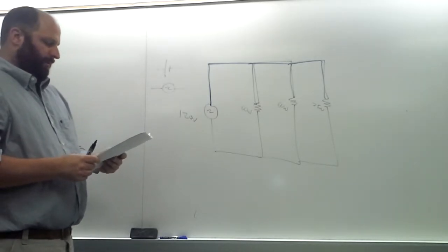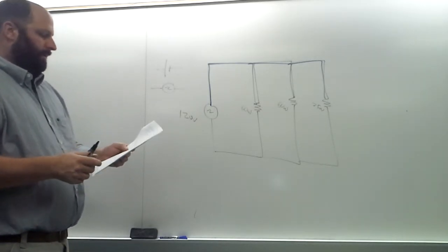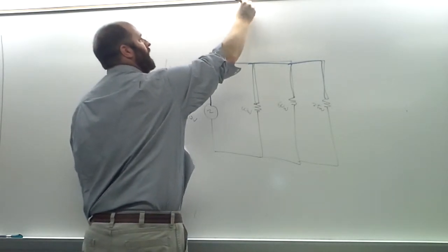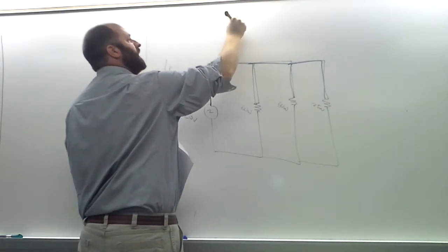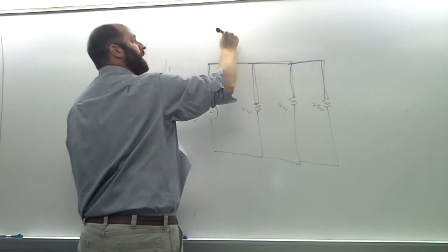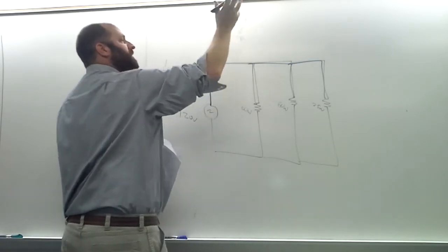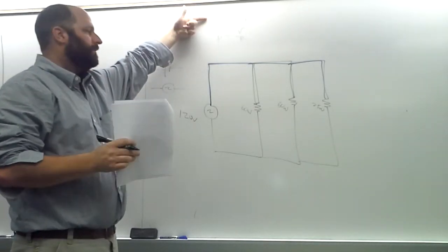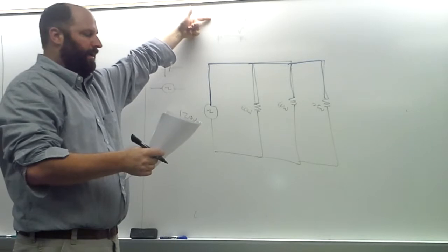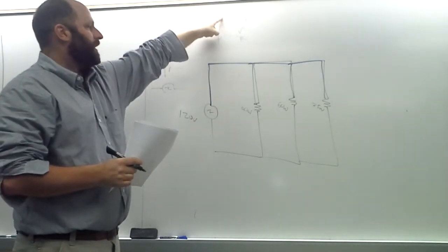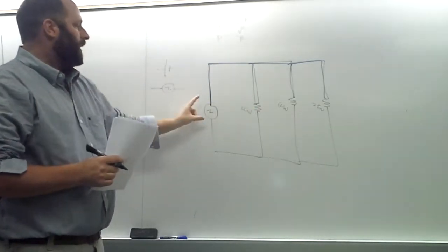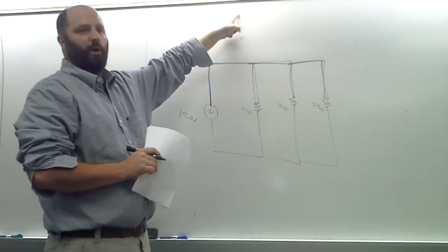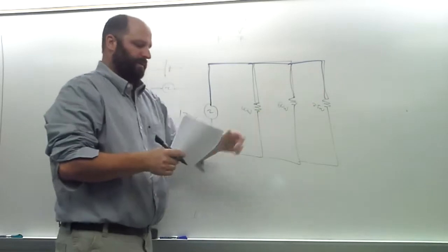Now, what we want to do is calculate currents. So power is equal to I times V, current times voltage, also equal to I squared R, also equal to voltage squared over R. These are the 3 ways power can be calculated. You probably only need one for most of these problems. I would start here. Put the 60 watts here. This is run off a blue to black, 120 volt potential, so that would be this number. That's how you find the current. And you do that same thing for this bulb and this bulb.